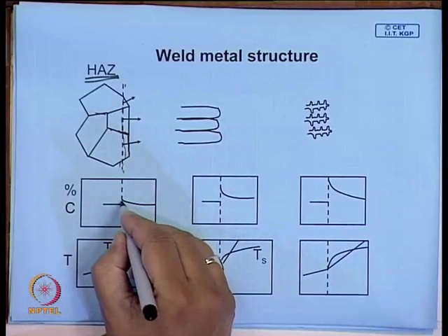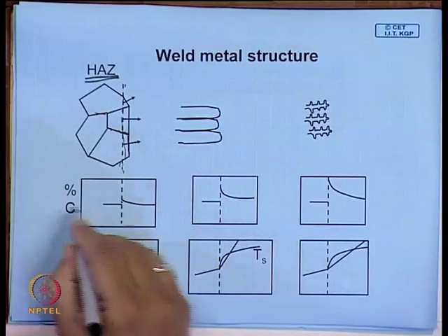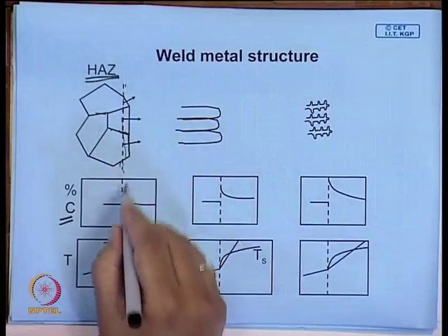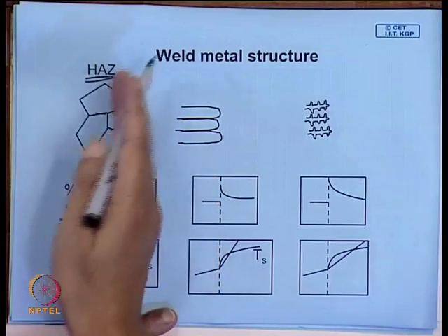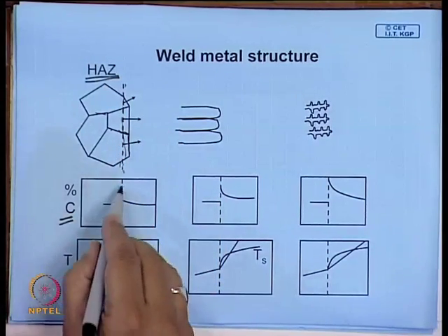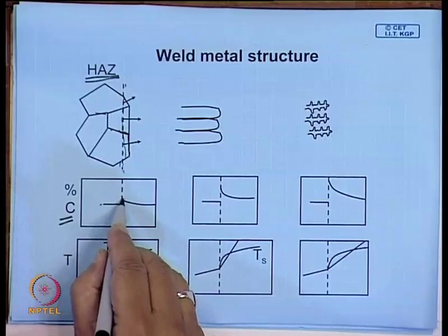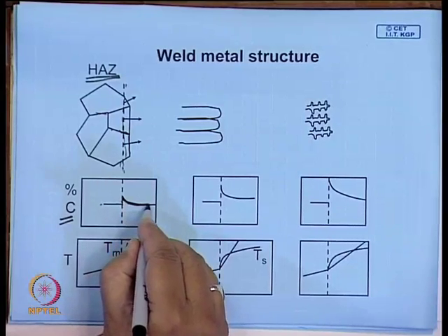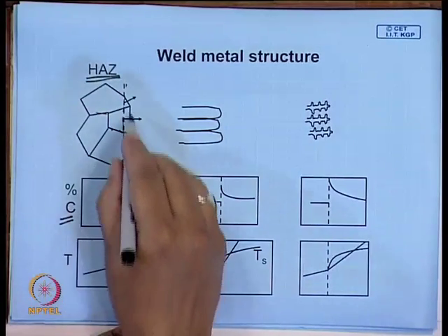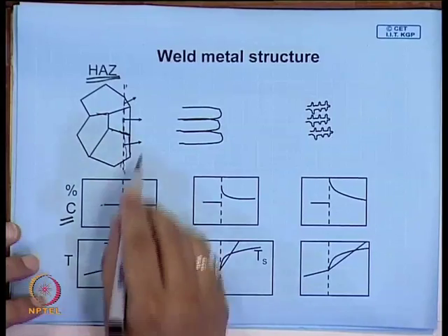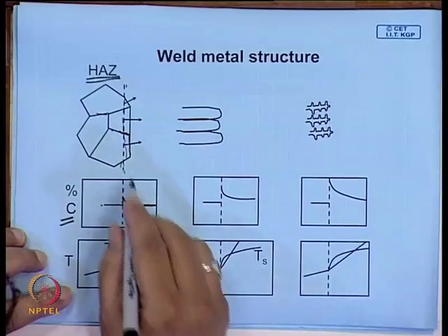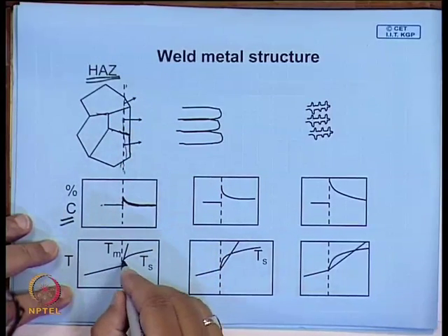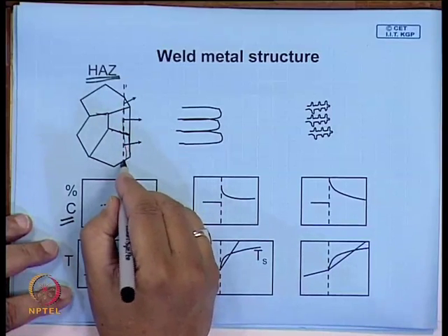And we have seen, if you looked under solidification, this is the kind of solute build up near that liquid interface, because the solid which solidifies first is purer. So, here this has a lower concentration of solute, and here there is a mix up. In fact, there will definitely be some mix up, but still there may be some concentration gradient in the liquid, and whether the front will be planar will depend on the gradient.